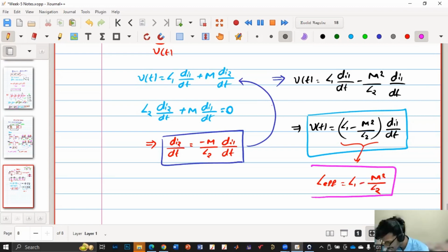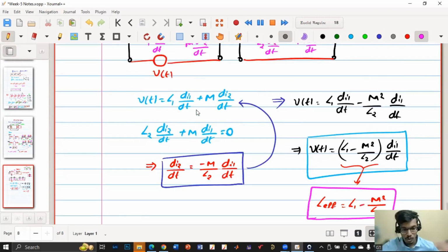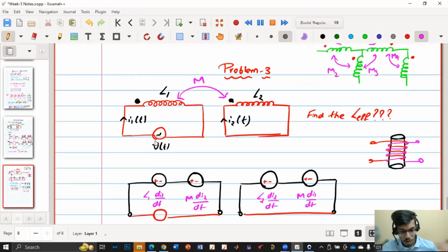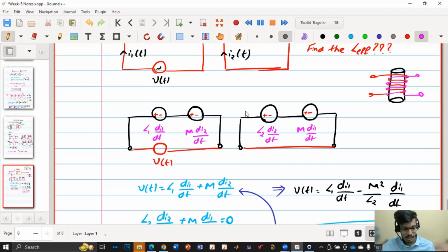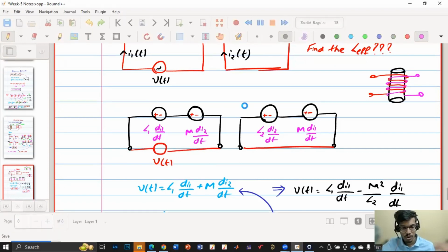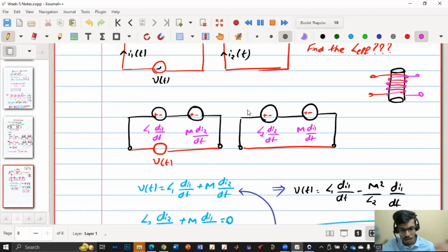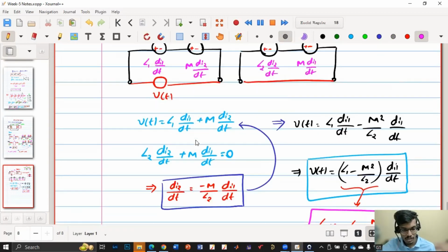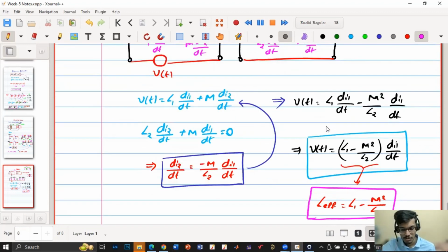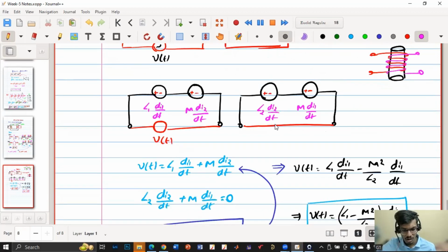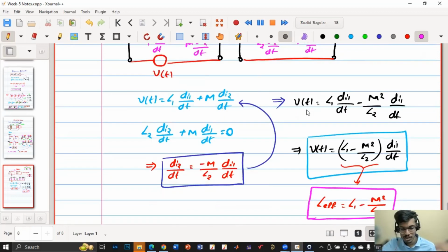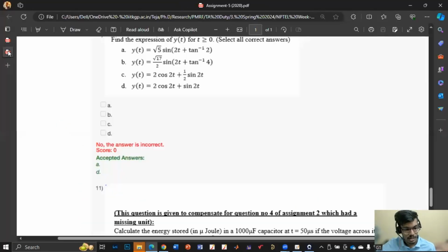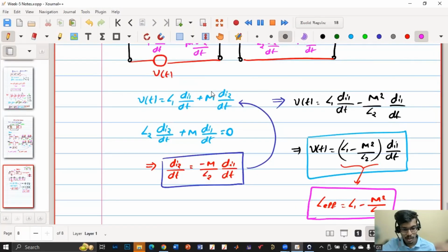For any such question, first we need to draw the voltage source with polarities. Then we understand this has plus minus with these values. If you want to write in phasor form, then di by dt becomes j omega I, j omega I2, so we replace by j omega. Else, we can just play with the equations to get I1 and I2. But the polarity is the main thing, the most important thing.